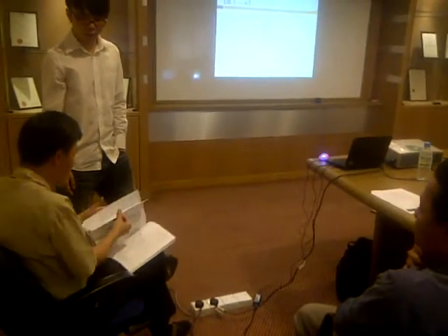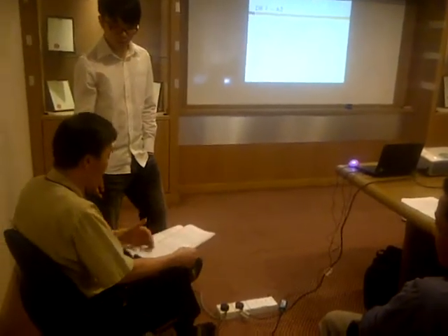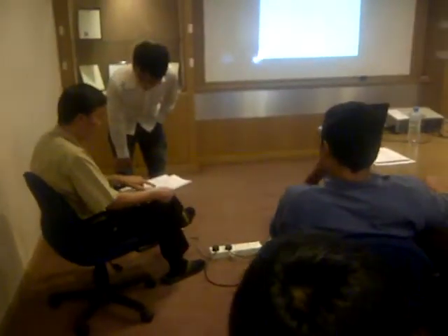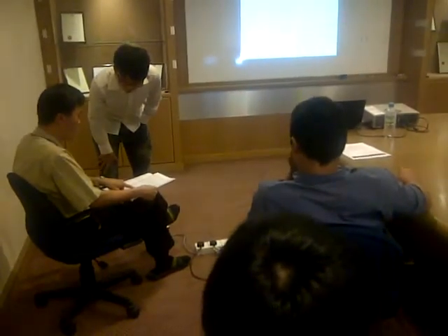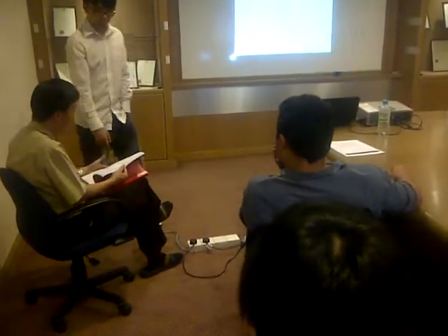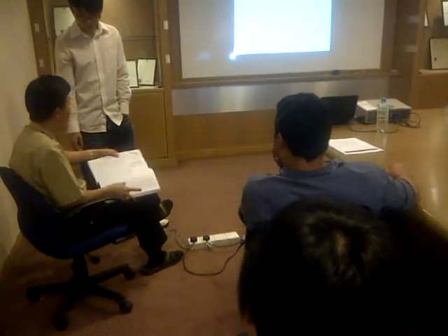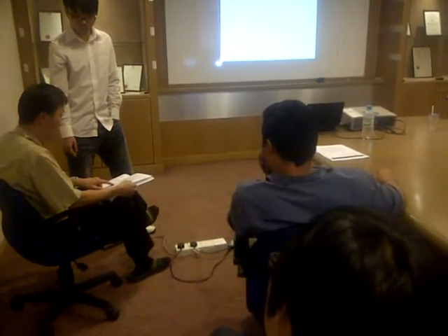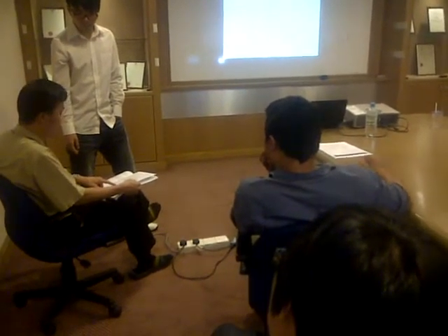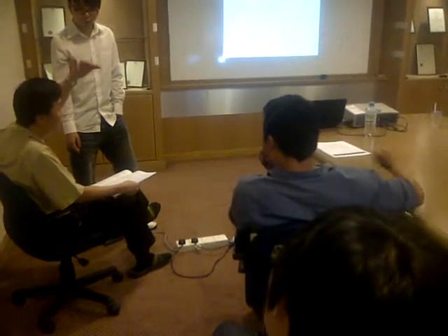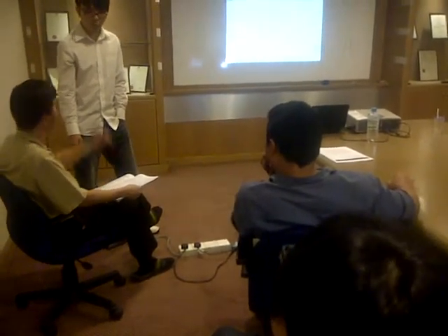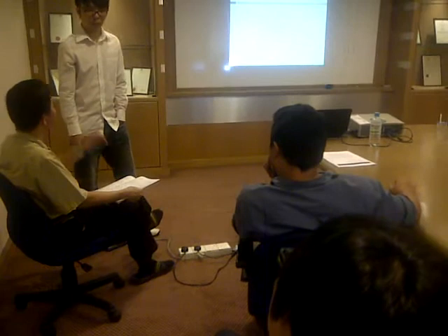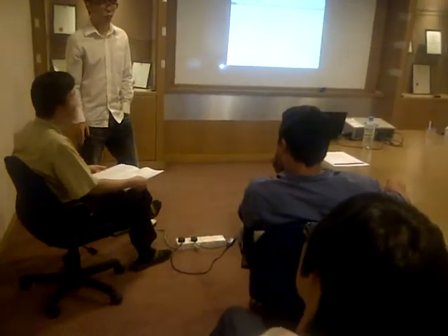So this one actually already teaches all the correction factors. You must know how to apply it. They tell you the ambient temperature. When the temperature goes up, your current carrying capacity drops, you only have to multiply. Let's say for instance, based on here, it is 41 amp. But let's say this one is hotter, for 35 degrees Celsius, you have to only apply 0.97. So the actual current is dropped a bit. Then you have to see if the current is still fulfilled. If you still fulfill, you can still use 6 mm. If cannot fulfill, you have to use one size higher.